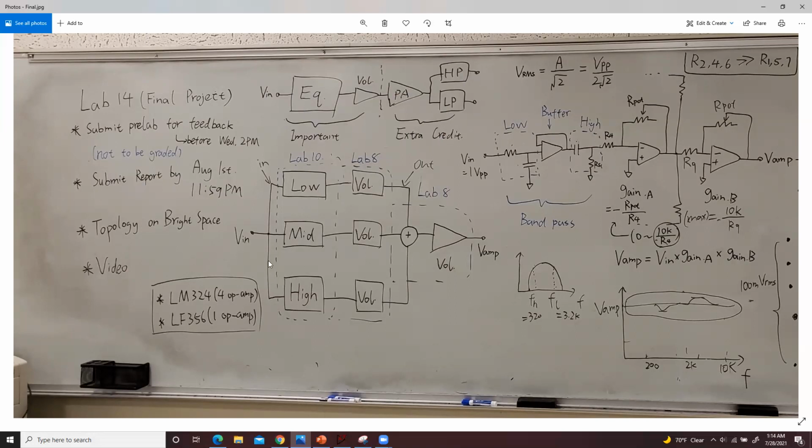Okay. So as I mentioned, this is a block diagram for the equalizer. This equalizer will divide the frequency into three different bands. So how can you divide the frequency? You will use a filter. Here is the low pass filter, you have a band pass filter, and you have a high pass filter. Filters help you divide the frequency according to their cutoff frequency.